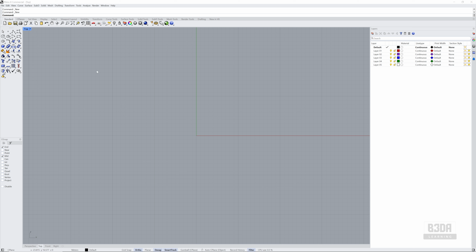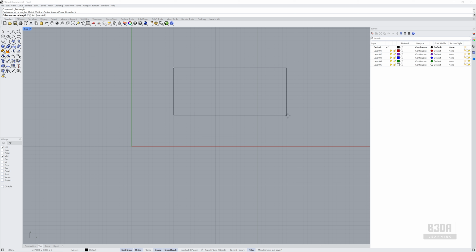And I will start with the design of just a simple room, a set of walls, and an opening for a door. I will start with a rectangle, and I can click anywhere here to get started. I'm using the grid snap. Let me click anywhere to get started here, like this point. And let's say I want to draw here a rectangle with 8 meters. I'm using meters here, 8 meters by 5 meters. So I just click on this starting point.